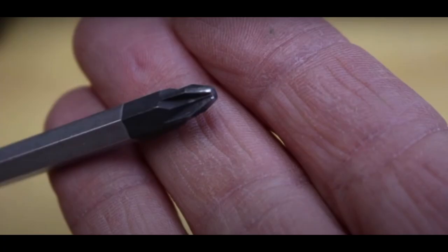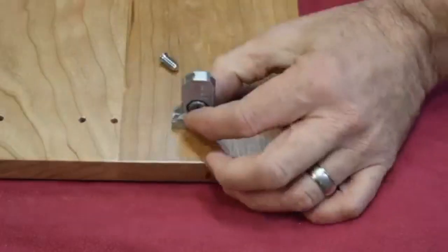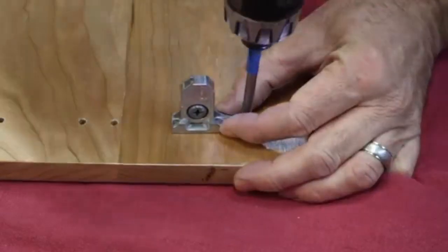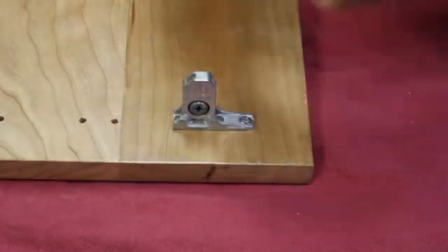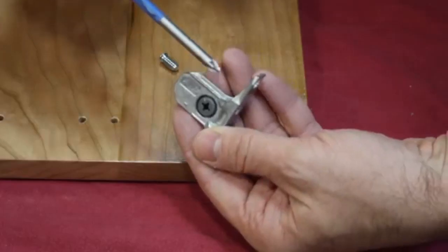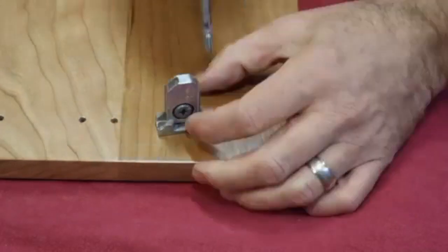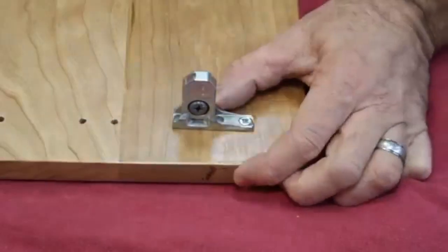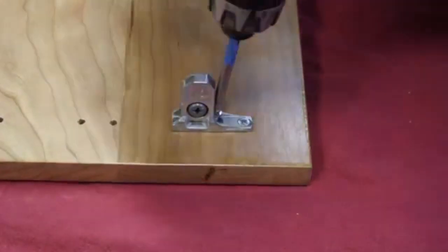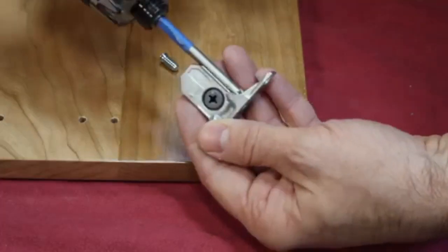Posi drive screwdriver. It is an updated version of the Phillips screwdriver. It has an additional four lines radiating from the center. The screwdriver has a blunt tip and small ribs along the blade between the main edges. With its design, it has a decreased risk of damaging the screw head. Moreover, it has a lesser chance of camming out.